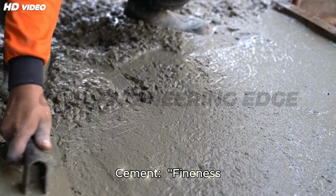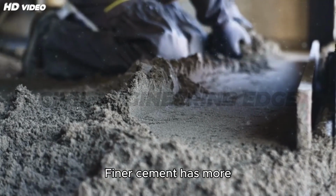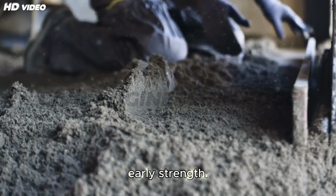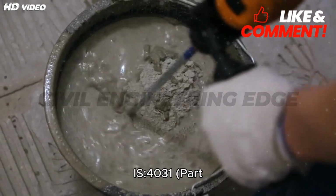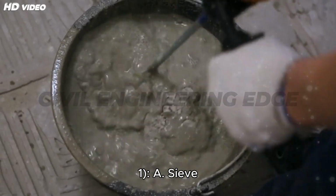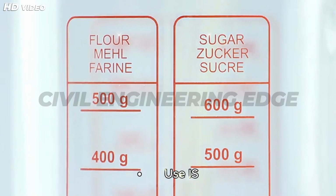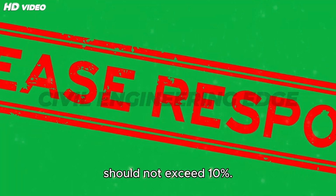Fineness affects hydration rate, strength, and workability. Finer cement has more surface area, reacts faster, and develops early strength. Two methods are permitted by IS 4031 Part 1. A. Sieve test. Take 100 grams cement. Use IS sieve 90 micrometers. Shake for 15 minutes. The residue should not exceed 10%.